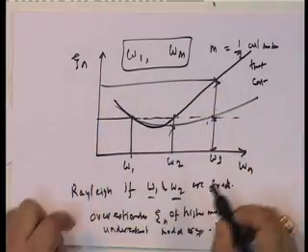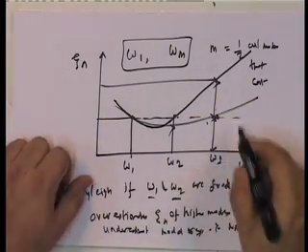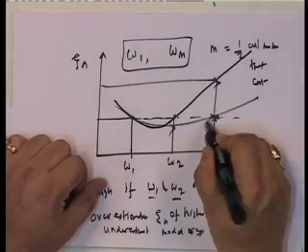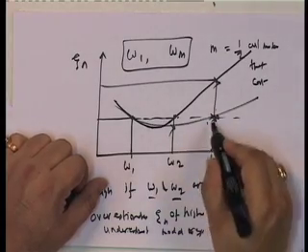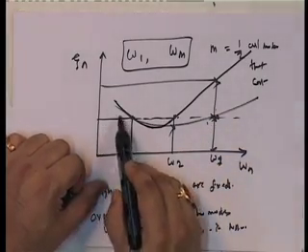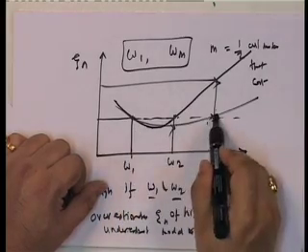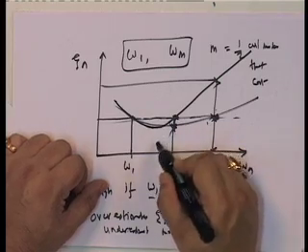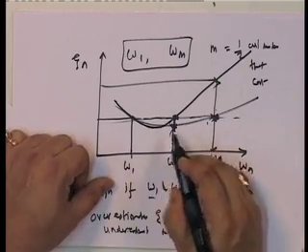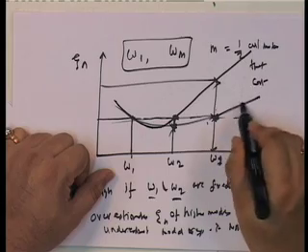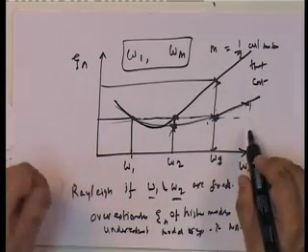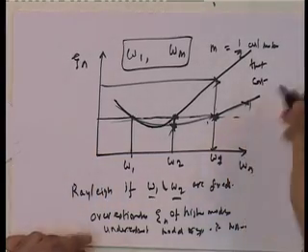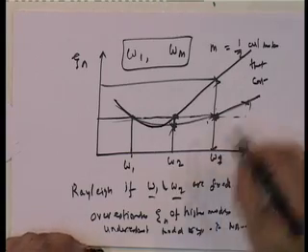Because then what happens is, if you take that mode, let's say 4 modes contribute and I take omega 3. Okay, if I take omega 3, what's happening is omega 1 and omega 3 are at 5%. Omega 2, the damping is underestimated, so its contribution is overestimated, and then the higher modes, omega 4 and all, their damping is overestimated, and therefore you underestimate their response.